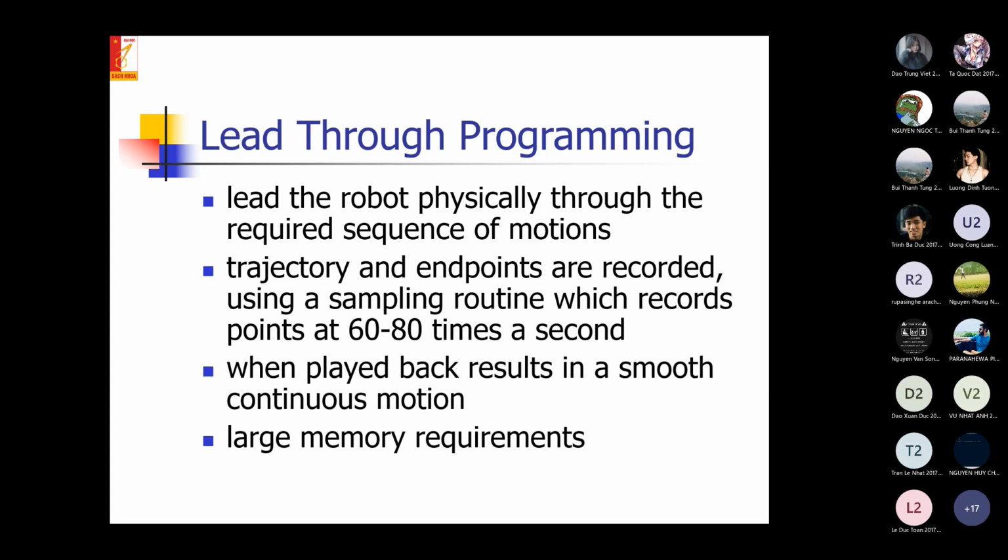Or, inside its workspace, if there are no obstacles, we can let it move freely from the start point to the end point. And by this lead-through programming, the trajectory and the end point will be recorded.